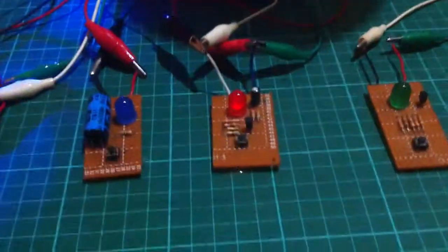This transistor is operating as a switch in saturation mode. When you push the switch here, current flows here, the LED turns on because also current flows here at the base, making the LED turn on. So that is the basic operation of the circuit. You can watch my previous video, our previous video, in this title. And let's go to the second circuit.